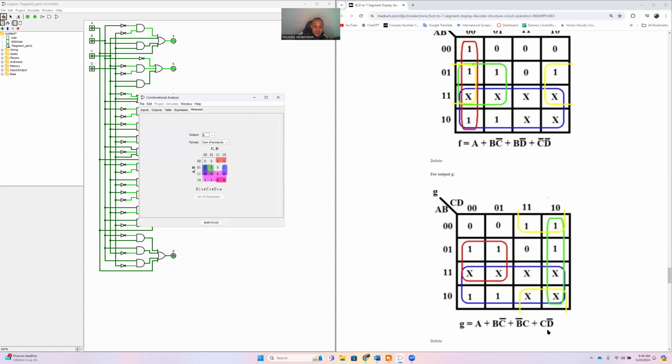Okay, you have another option. You know that the Karnaugh map is continuous, they are connected, so that edge is connected to that edge. It's like that, and that edge is also connected to that edge. It's like that. So you can consider this x as one and this x as one, then take a square like this, similar to this yellow boxes, one like that and one like that. So take these two with these two. This is what happened with the magenta color here.